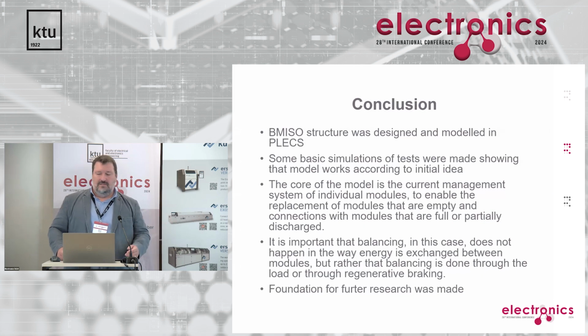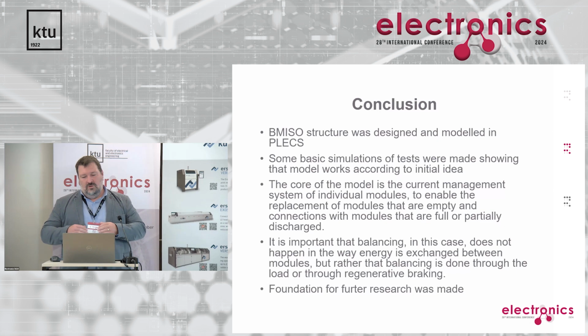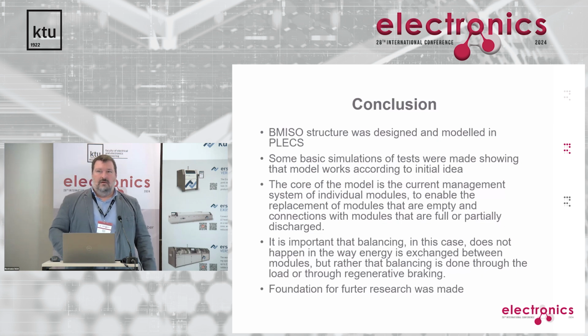We did some basic simulations just to test the current controllers. The current controllers are very important here, especially at those points of transition, to assure that current flows very smoothly and you don't have any shocks. As I said, current management is very important here. And of course, with balancing, almost everything here is programmable.